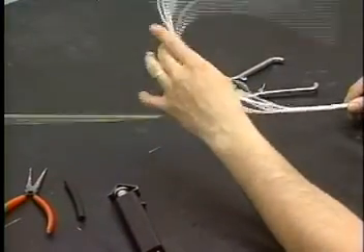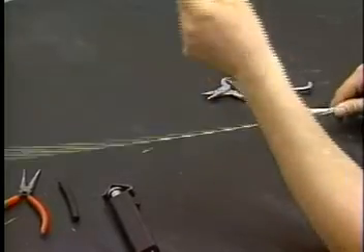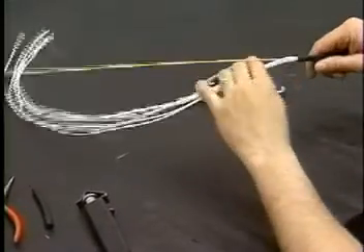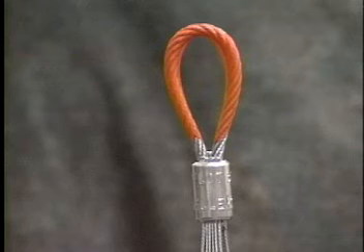Fiberglass epoxy rods may be secured to the pulling fixture with tight clamping plates or screws. If the cable has a central steel strength member, a small length of it may be formed into a pulling eye and attached to the pulling line.